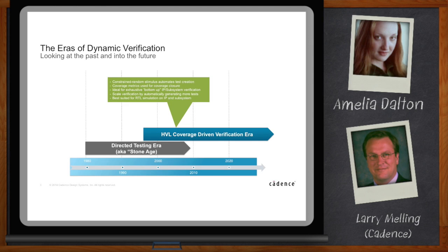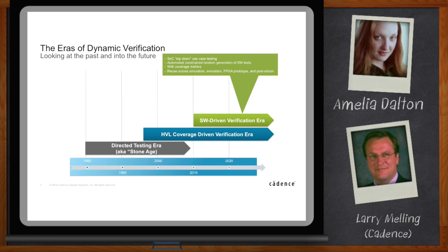But when you start putting the SOC together, it becomes a different issue, because now you've got hundreds of different pieces of IP, all this stuff coming together, and the space becomes so large that an exhaustive test isn't practical. And that's why we keep referring to this whole use case thing, the idea of creating a top-down level use case, but we don't want to go back to the old days of saying, here's a directed test, and there's no metrics behind it or anything else.